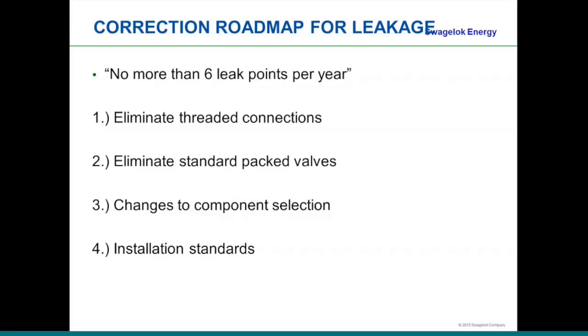The fourth thing is installation standards, having a standard when we put the components in, so always the components go in the correct way. So there's your roadmap for correcting steam leakage. But I'm quite serious that no plant should have more than 6 leak points per year for steam leakage. We have the technology and the way to stop steam leakage.